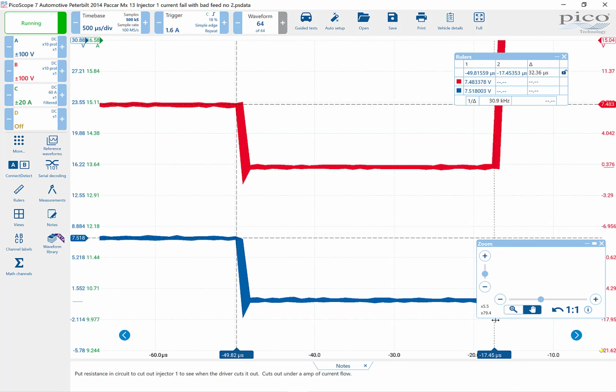So by knowing that on known goods, this will help you. If you have a bad one, let's say, for example, that as soon as it closes it either takes way too long to fire, or it fires and it's not enough voltage, then that's indicating to you that you've got something going on inside the ECU. Could be the driver, you might have low battery voltage to the computer, but it just gives you a good direction to go to find the problem, okay?